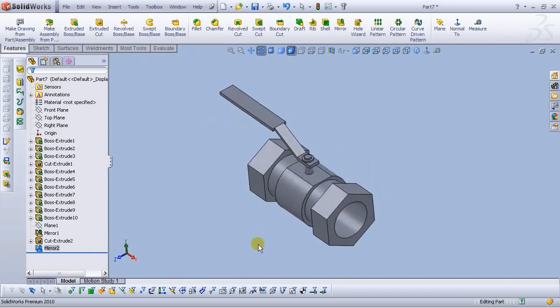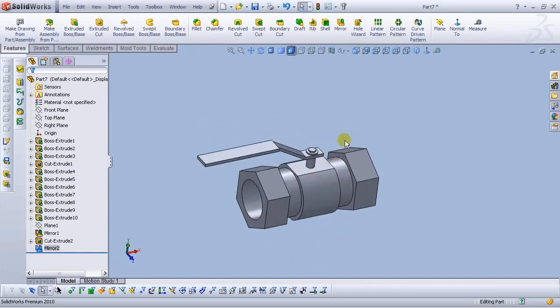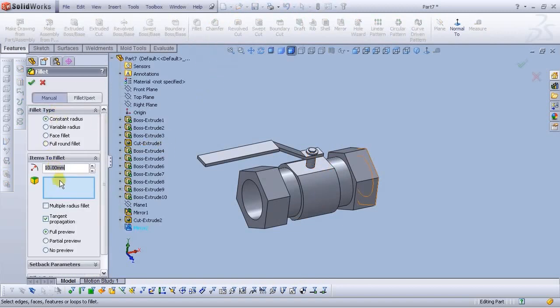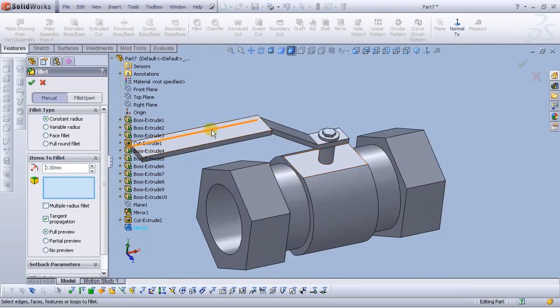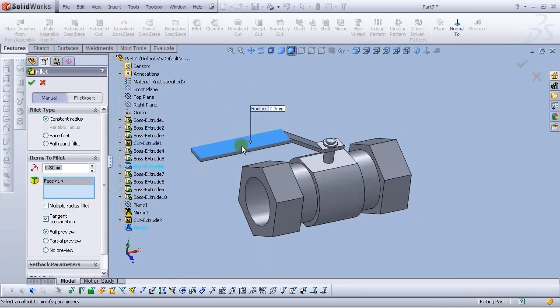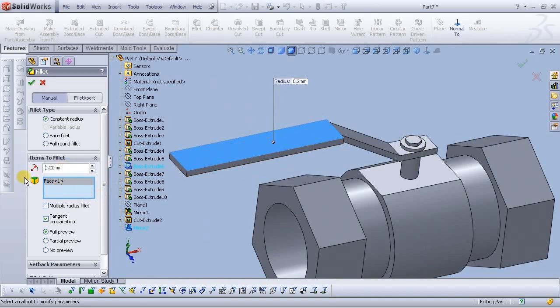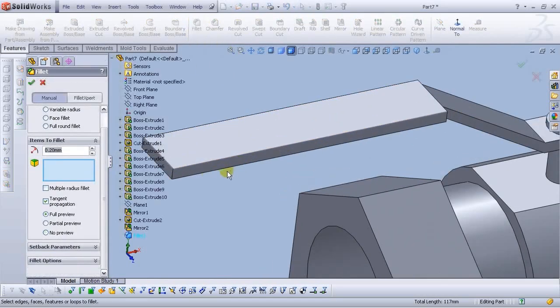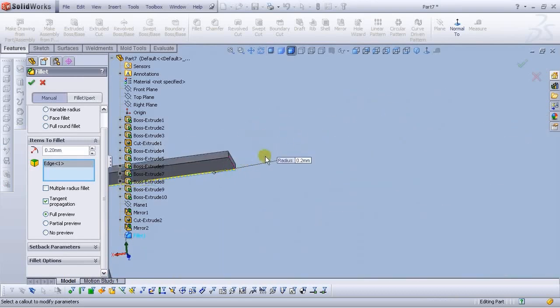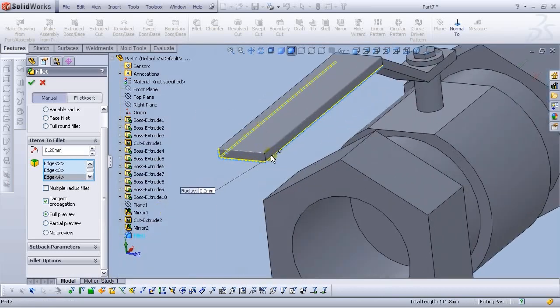Okay, let's make tangent this line and this edge here. Okay, and let's make these points vertical. Okay, and let's smart dimension this. Now let's type 35 millimeters. Okay, go to the features, extrude boss base, and select reverse direction. For the depth, type 15 millimeters and select OK.